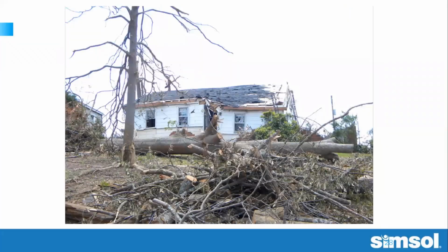Now, what do you think of this one? Again, somebody started cutting some trees up here. There's no leaves left on the tree that we see standing. It looks like this house was hit by something. You notice the roof line at the eave is a little out of level there. But again, look at the damage to the roof structure and on your way down the wall. And notice that the wind damage is primarily on the eave of the gable end, pushing backwards, which is where we'd expect to find the wind damage in that pattern along the eaves, the ridges, the discontinuities in the roof line.